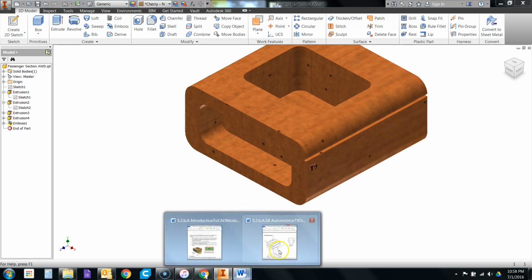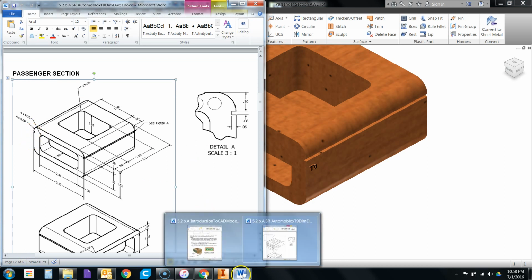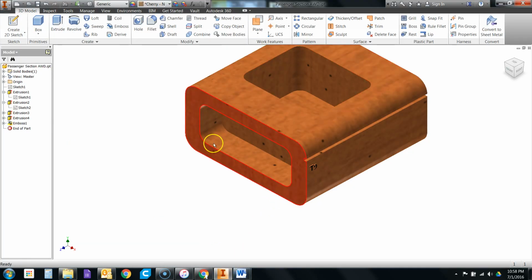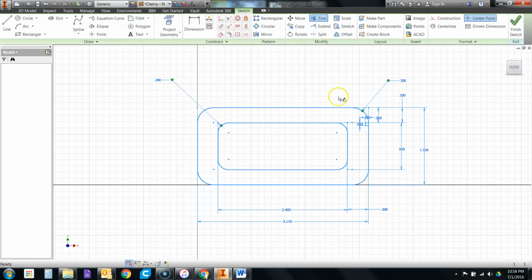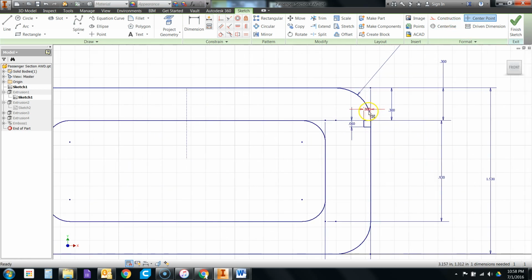But if you'll notice, there's also one on the other side. So, how do I make that work? Well, I think the easiest, quickest way to go about doing that is that since they're on the same side and they're with the exact same dimensions, when I worked with the sketch, I could go in and draw a line, make it a construction one, find the midpoint of the top edge, click, and just drop down a vertical line. Doesn't need to be any particular distance long, as long as it's vertical. That's what we're looking for. Turn off my construction.